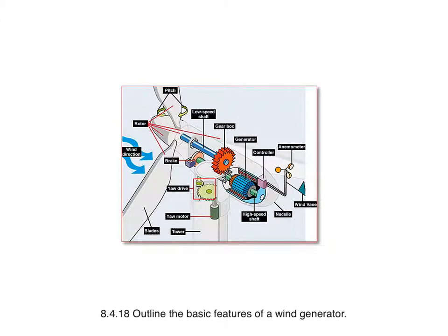Here's what's happening in a bit more detail. Okay, so we start with the wind, and the wind is causing a turbine blade to turn. And as that turbine blade turns, that rotates a shaft, which through some reduction gears causes a generator to spin. And those spinning wires in a magnetic field, by Faraday's law of electromagnetic induction, give us electricity.